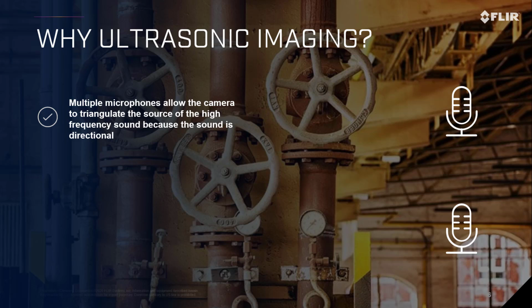So why would we do ultrasound imaging as opposed to just standard ultrasound? The key here is that we're using multiple microphones in our Si124 in order to triangulate the source of that sound. We create a sound map and then superimpose that map on a visual image, which allows us to easily describe the intensity of the sound source and where it is in the piece of equipment.